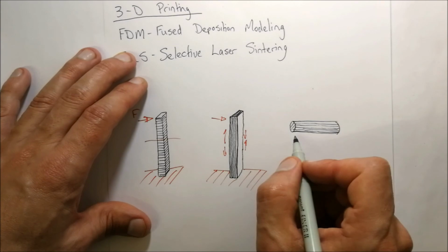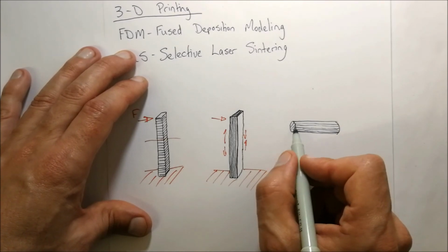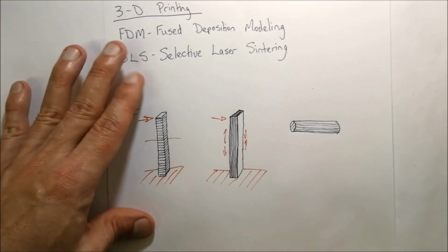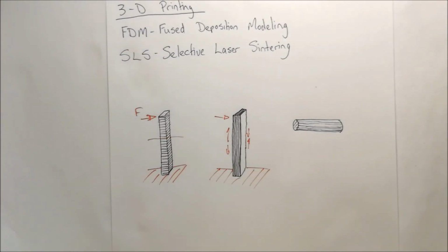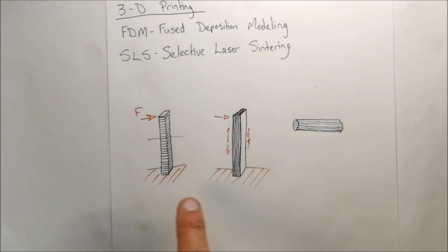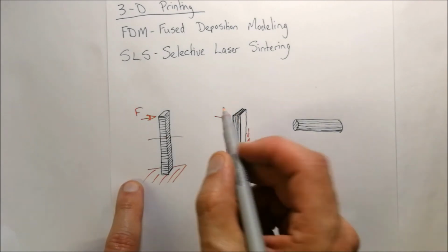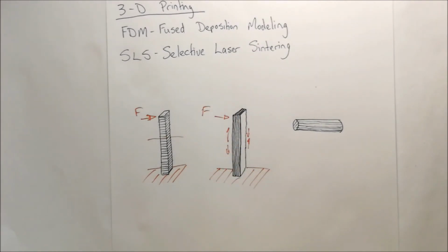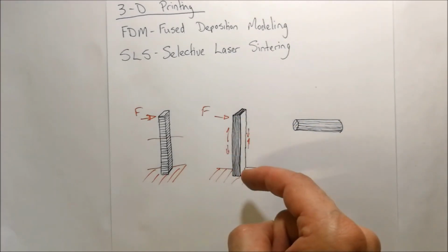That's often just removed by a screwdriver or a drill bit or so, but it might need to be done. So again, the amount of time it's going to take to machine a tube out of plastic might be 15 minutes or so, while if you have to 3D print it, it might take about a few hours. So it's very important to keep that in mind. Also very important is the orientation that you're going to 3D print it, because you've got to look at what forces there are going to be. If there's going to be a force applied to the material, it is best to make sure that the orientation, or the way that it's printed, is at 90 degrees to the force.